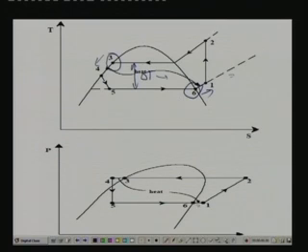The same thing is shown here also. So you can see that this is your process of subcooling and this is the process of superheating. This is your superheating, this is delta T superheat, and this is your subcooling. So what is the effect of subcooling and superheating on the system performance? Immediately one thing is clear, that refrigeration effect has increased.